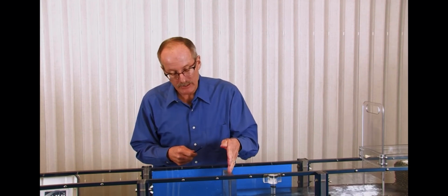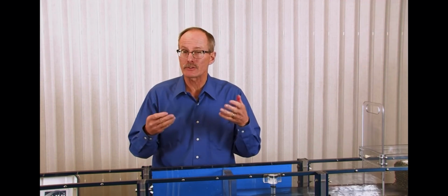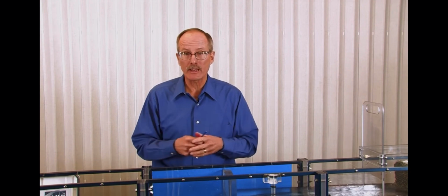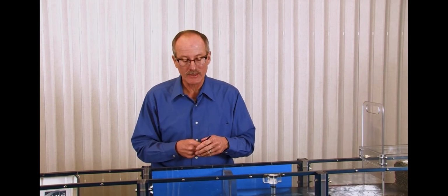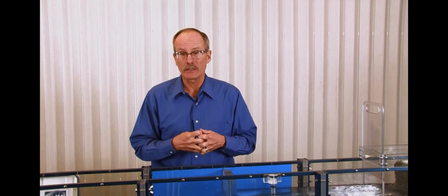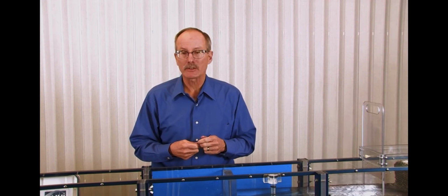This demonstration illustrates why it's important to think about the entrances to a culvert. That's why we at times want to bevel the headwall of our culvert entrances, because it can affect the headwater as it enters into the barrel. So the orifice equation is a common equation used in highway drainage design.